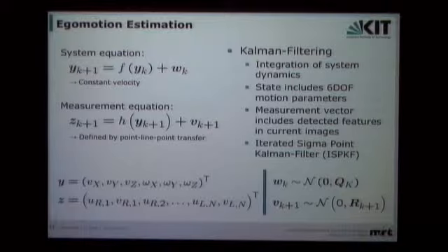And the important point now, the crucial part, is that the measurement equation can be used via the trifocal tensor to predict the position of the features. If this is known and the time between the two stereo camera frames is also known, the rotation matrix and the translation vector can be computed between these two camera frames. And since we already know the rotation matrix and the translation vector between the two single stereo cameras, one can construct the trifocal tensor as mentioned on the previous slide.